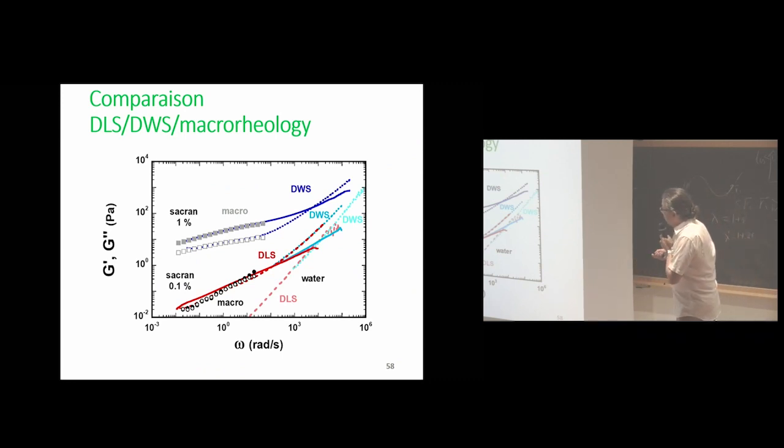And we can compare microrheological techniques and classical shear macrorheology. The macrorheology data were taken by Guillain, so you can see these data points of macrorheology, and all these colored curves from microrheology, and they superpose reasonably well for this system. It can cover, let's say, 10 to the minus 2 Pascal, but it's getting less accurate. At higher modulus, it can be thousands of Pascal. At 10 kilopascal, it's already very difficult, as we use only the thermal energy kT. When the system is elastic, the displacement can be too short to detect even with DWS. So we can check the validity and accuracy of the technique by comparing with macrorheology.